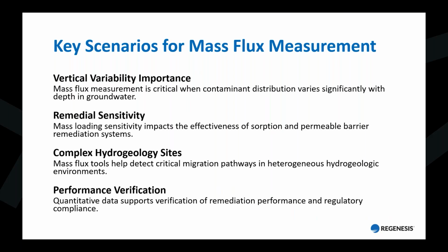With remediation, there's a lot of sensitivity, particularly with sorption or permeable barriers, to what the loading is coming into it. So having that understanding of what the range is is really critical for your remediation design. Also, in complex hydrogeological systems where there's some heterogeneity, again, it's critical to understand that for our design.